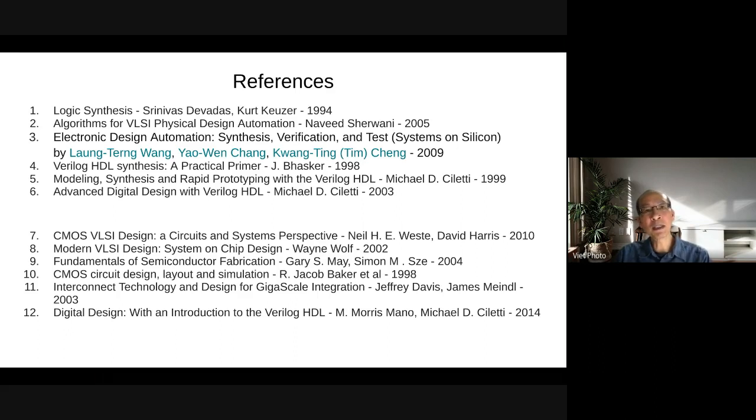The input would be thousands of inputs, and you can imagine a system of a billion transistors. So the factorization or minimization is very complicated. However, those things are quite mature. After they factorize and optimize the equation, that's the 3 steps, the main things in logic synthesis. After that, they do the mapping. They map those equations into the cell library, which has NAND and NOR gates, adders, memory, and so on. That's all covered in the logic synthesis book here.